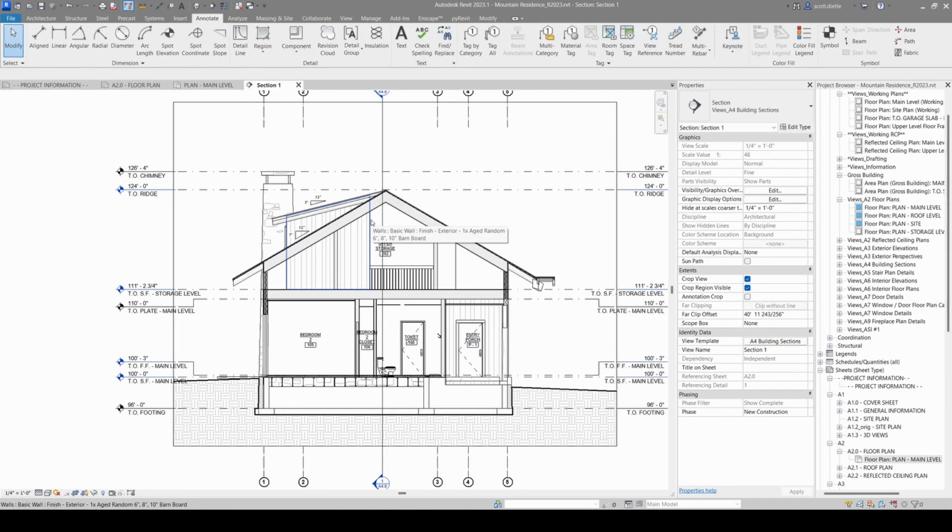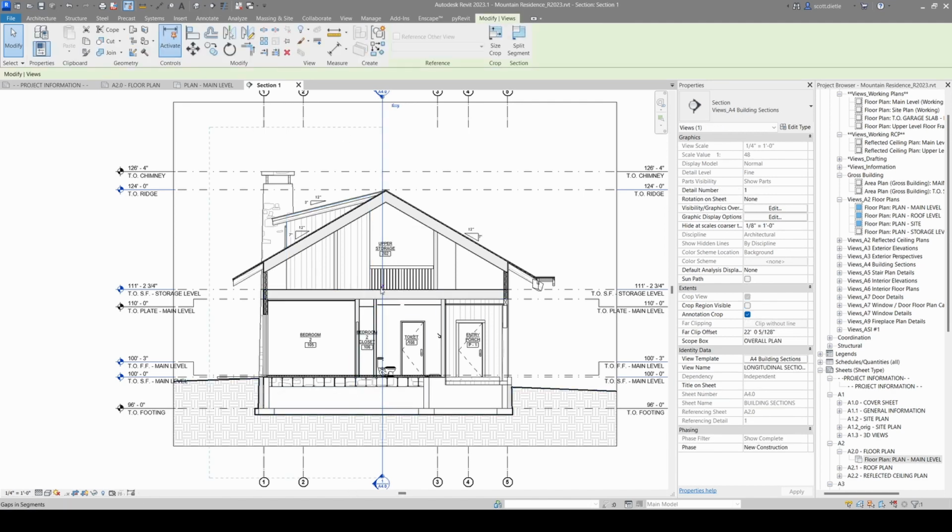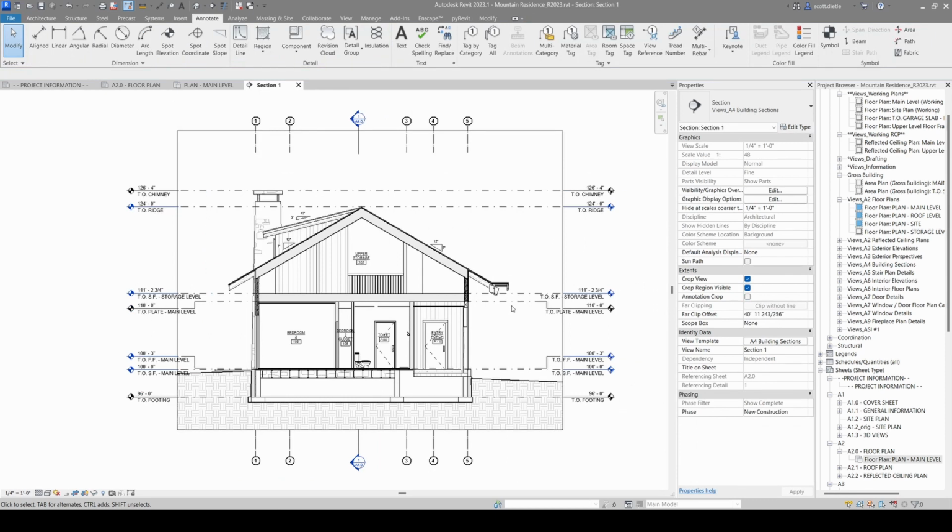So we've got our levels, we've got our grids, we've got our section callouts. I'm going to break this section, actually. We'll go up to here. Bring this one down here. I always try to keep grid heads, section heads, ends of section lines, level heads, all lined up. It indicates intent of drawings that were put together well.